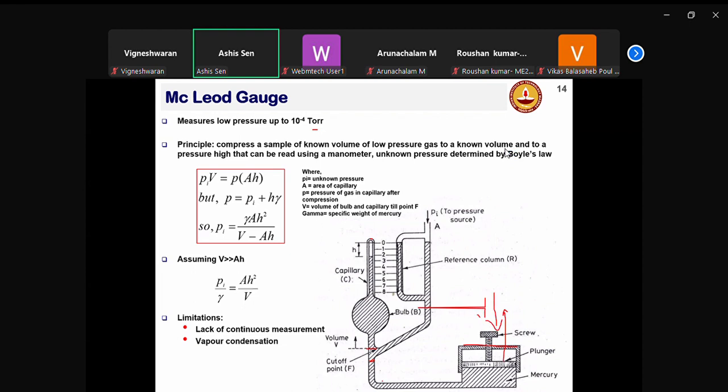When you move this plunger down, this amount of the source fluid is trapped. The mercury goes up here and fills everywhere. Essentially, the fluid, which was initially at negative pressure in this volume, gets compressed by this rising mercury